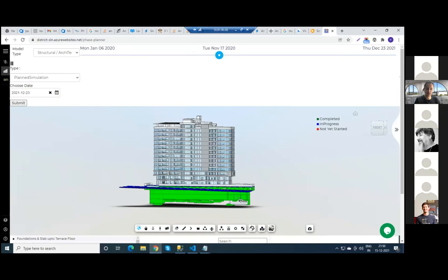One option is to skip the property DB and then grab the information for each ID, in other words, the phase information, and pull that into your own database. So you'll have a database that has the objects' DB IDs, and each DB ID will have the phase. And then as you change that slider, you'll query your database to find out which IDs to colorize.